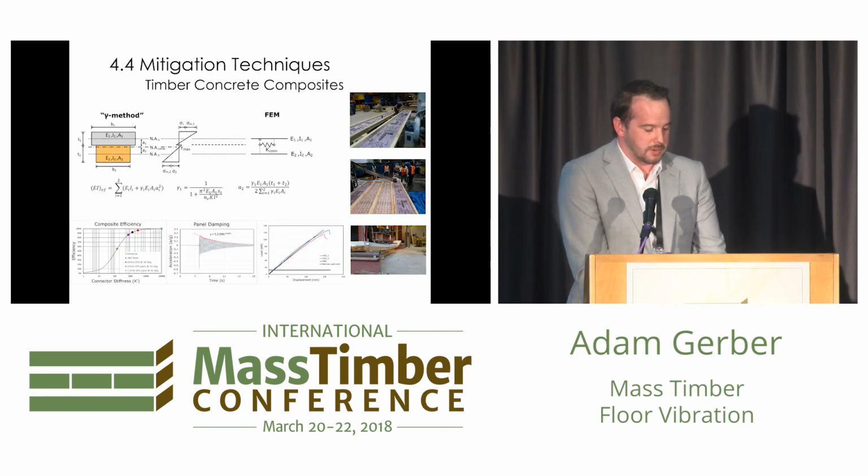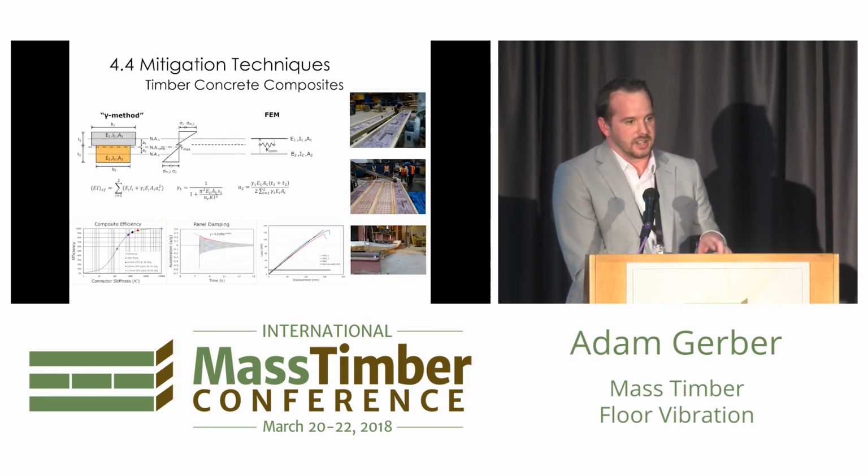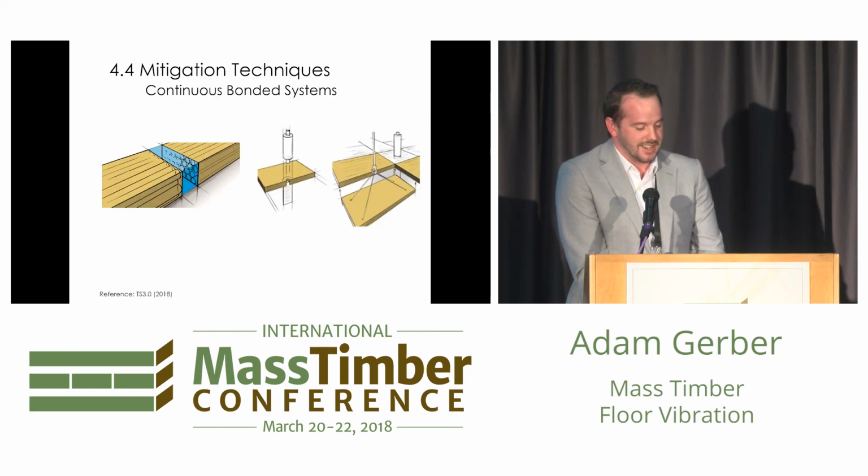So without spending any time on it, timber concrete composites could be a whole session all on its own. It's one good way to add mass and stiffness, and we utilize it definitely in cases where we're into a really slender floor. Some continuous bonded systems are being investigated as well.